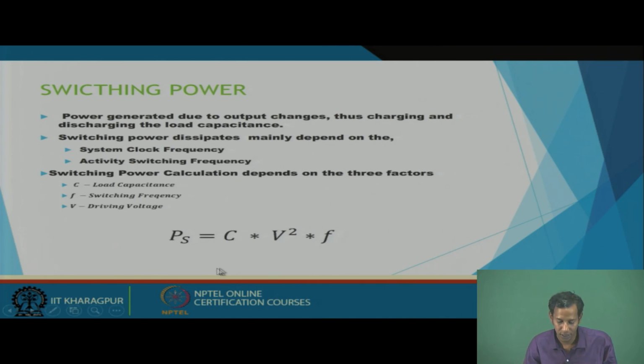Then again, this depends on the capacitive load. While you are delivering more power, if your capacitive load is more, at that time you will consume more power. At that time your driving power should be more, so that you can distribute the power constant output to the other circuit. That is why you need more power consumption, rather than if you are using a lesser capacitive load.